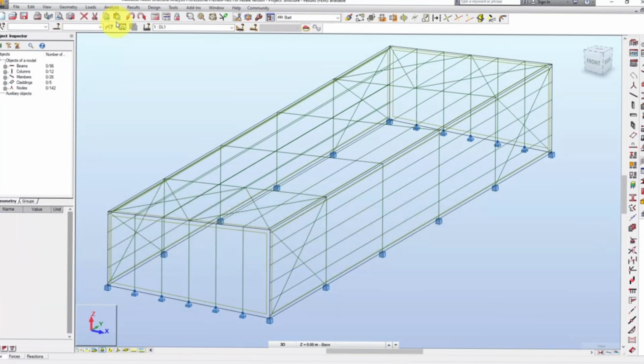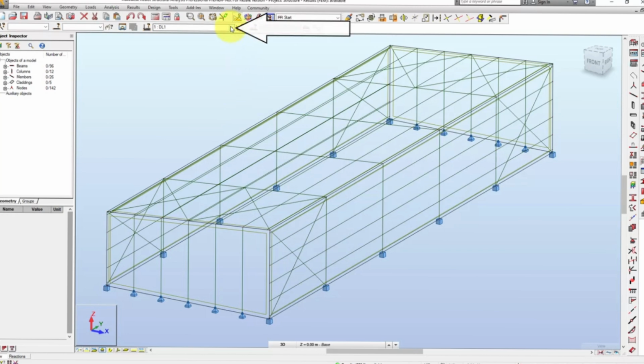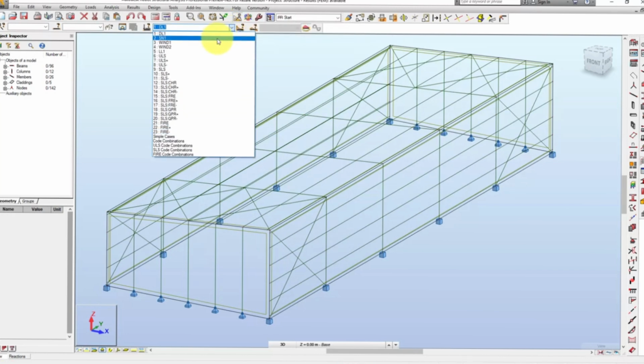Once the analysis is complete, a notice that FEM results are available appears both at the top and bottom of the program. Each load case combination will now have computed stresses and strains based on generalized section forces. To inspect the results, from the toolbar, expand the Cases dropdown and select either a simple load case or a combination load. In this case, the simple wind case is selected.